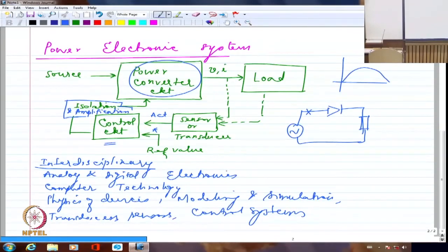For example, our power system is supposed to be a very weak power system because most of the times our demand is higher than the supply. The demand is always larger than the supply, because of which voltage sags. Voltage will not be at 230 volts or 240 volts. It may come down to 180 volts. So the equipment which is expecting 230 volts, if it gets 180 volts, it's not a good thing for the equipment. So our power quality normally is not good most of the times.